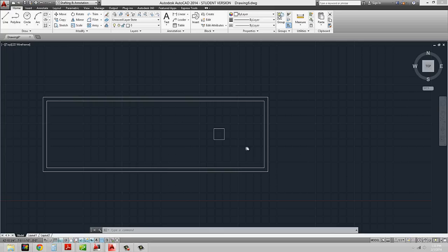What you can also do is, if I have, let's say, a vertical construction line, so XL for construction line, V to constrain it to the vertical, and I'm going to set it off into the distance. You can either stretch it arbitrarily from that base point, or you can type in the command as I did with that 1 foot. But if I don't want to go by a measurement, I can use my stretch and snap to an object in order to snap this portion to this object.